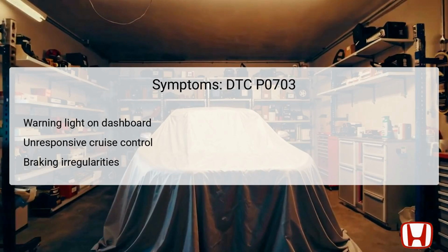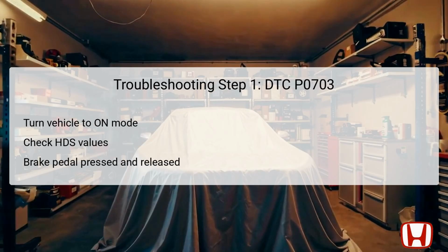The first step in troubleshooting DTC P0703 involves preparing the vehicle for inspection. Start by turning the vehicle ignition to the on mode, which powers the PCM without starting the engine. Once in this mode, it is crucial to check the Honda Diagnostics System HDS values for the cruise brake switch, idle stop switch. This requires pressing the brake pedal and then releasing it, while closely monitoring the HDS readings.